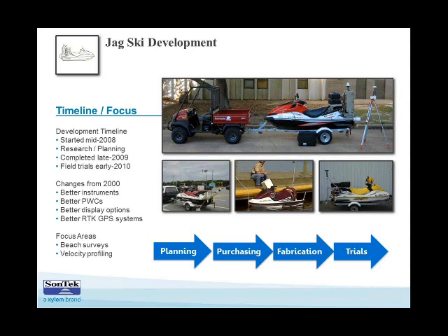And so if Isaac will, with his magic mouse, click on the video, all I did was essentially use HydroSurveyor software's native survey playback capabilities to record and clip out a small snippet of a survey. You see some of the parameters changing, the little red boat going along the track line, the signal to noise ratio over the depth at the bottom, and the compass parameters at the right. So it's just a little playback of actually conducting a survey.